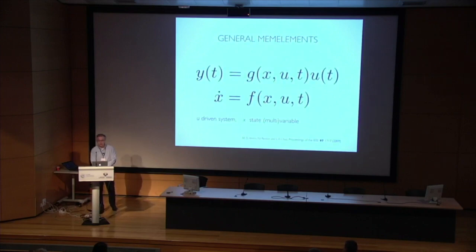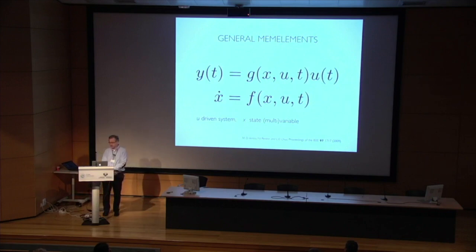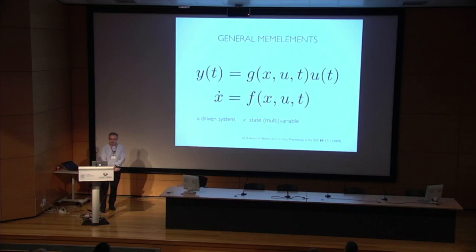General MEM elements will be described in this way, where U is the driving element of the system. In the previous case, that was the potential, and X is a state which can be a multi-variable. And there is a generalized conductance, if you will, or resistance, or whatever the case might be, and the state variable is going to obey some dynamical equation.